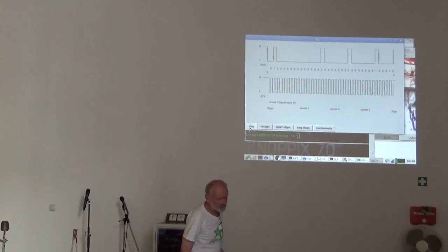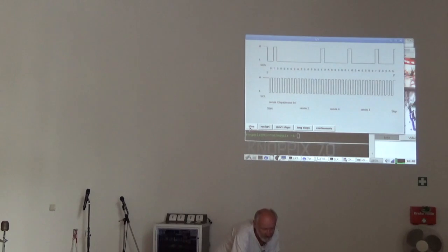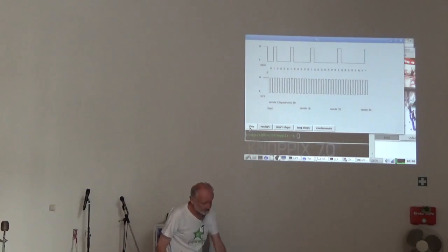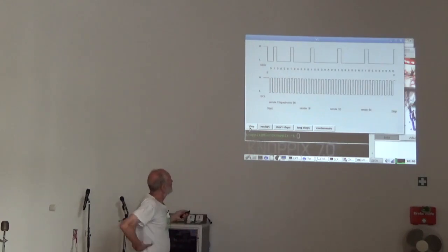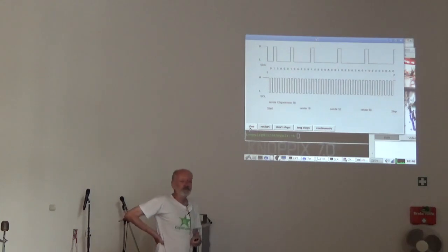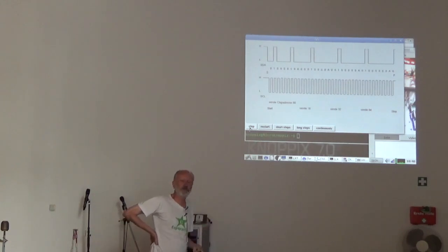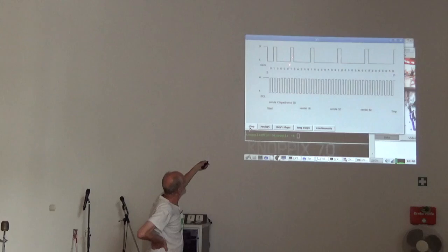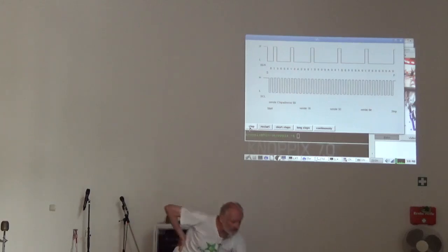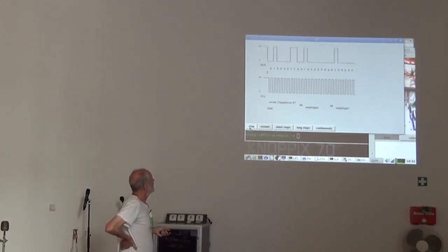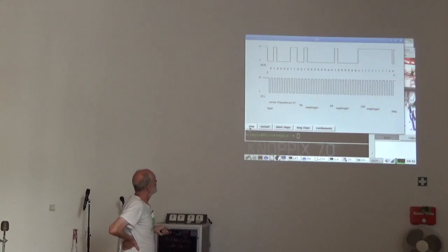Yeah, so this was the first chip, then the second. Okay. And so you see, when I want to have the chip in writing mode, I send a 0, and when I want to receive data from a chip, I send here as an 8th bit a 1. So let's hope that it will now correctly find the data. Yeah, now it works.